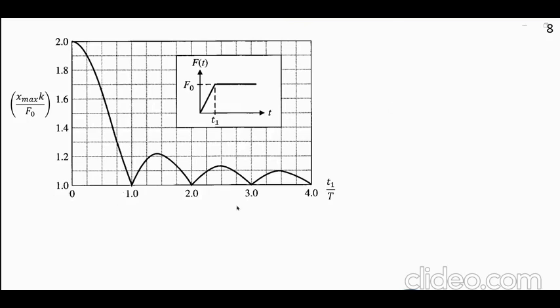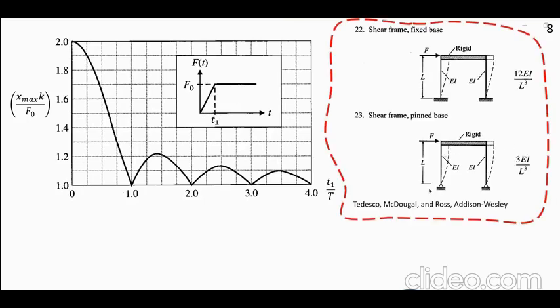You can see that. When it's a suddenly applied load, you drop the hammer, T1 is essentially 0. So you're at that location, and the block feels double the weight of the hammer, essentially. Okay, let's move on.